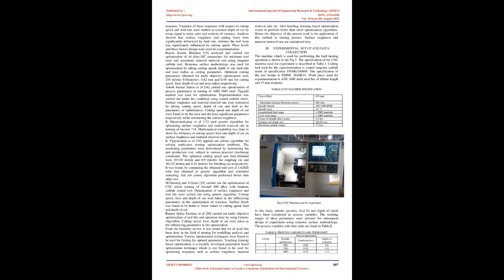[13] analyzed the effect of cutting speed, feed, and depth of cut on surface roughness in the CNC turning of AISI 304 austenitic stainless steel using coated carbide insert under dry condition. Taguchi-based response surface analysis was used for the optimization of surface roughness, both Ra and Rz. Mathematical modeling of the surface roughness as a function of cutting parameters was carried out using response surface methodology.